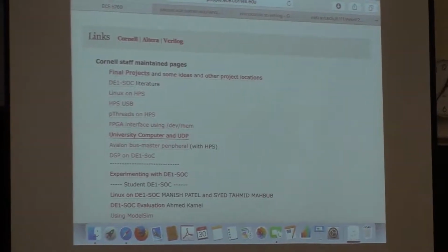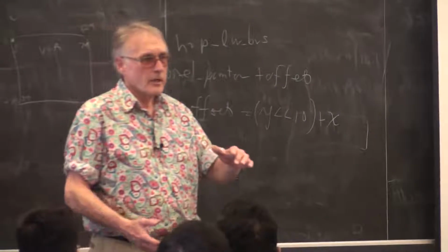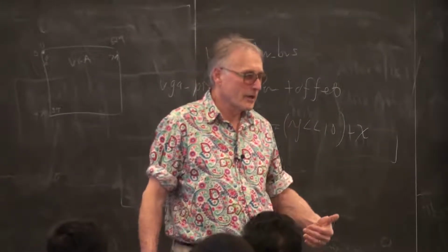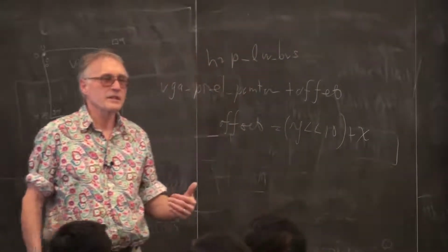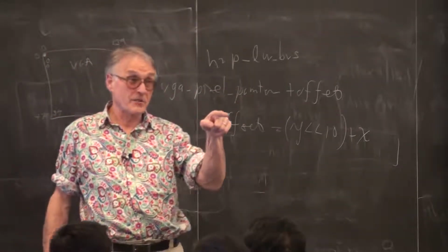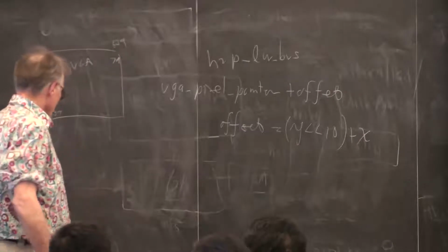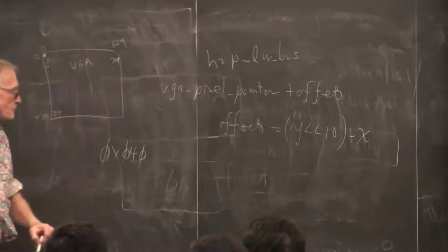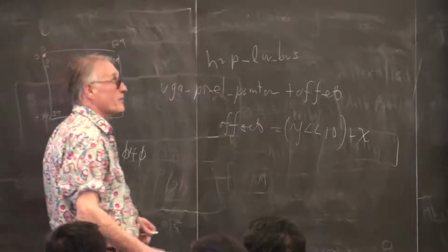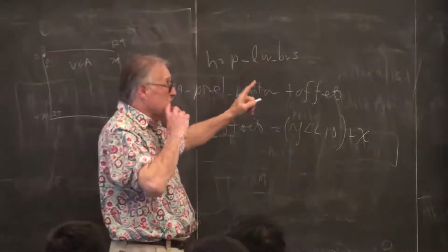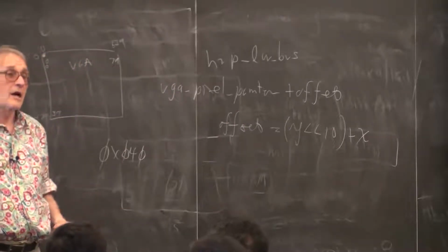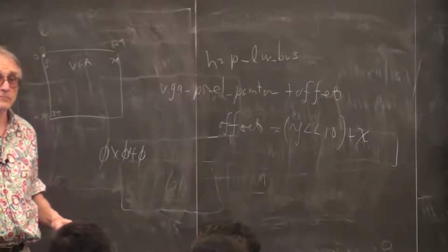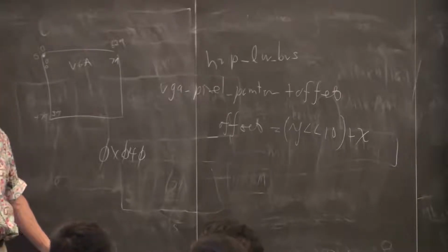The Qsys that describes the university computer, scaled to the screen, is about as tall as I am, so it's very difficult to show on an overhead. But the hexadecimal offset that you will get when you look at that Qsys file will be 0x040. So 40 bytes above the bottom of the bus definition are the switches, and that's obviously read-only, because if you write to it, it's not going to flip the switches for you. Well, wouldn't it be nice if it could?